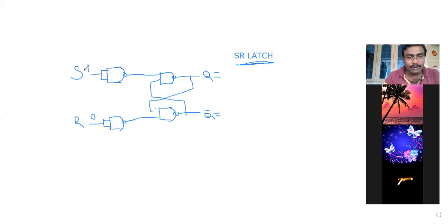Now tell me, guys, when this 1 is passing through this NAND inverter, what output will reach here? 0, sir. And I'm writing that 0. What about this one? 1, sir. Okay, now let us assume 1 is available in here. That means this is my previous state.